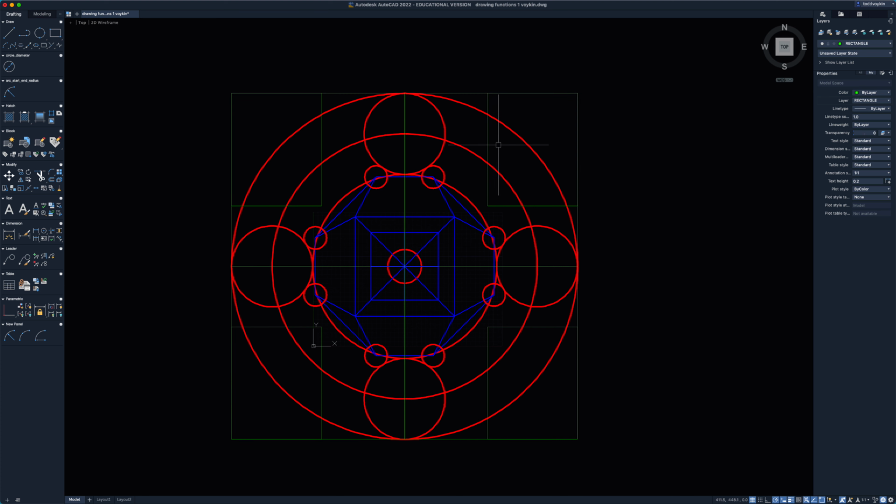So we're going to this time go into the rectangle command, but there is a little white box in the instruction section that we see in the middle of our screen right there, and if I hit the down arrow, it brings up 5 different options. So there's one that says chamfer. So I'm going to choose chamfer, and it says what is the first chamfer? Well, I'm going to choose 20. Hit enter, and it's saying, what about the second chamfer? Well, I'm going to do 2 chamfers of 20, so I'll hit 20 again, hit enter,